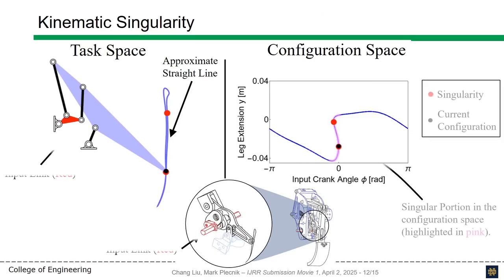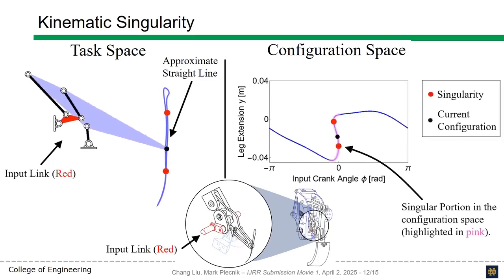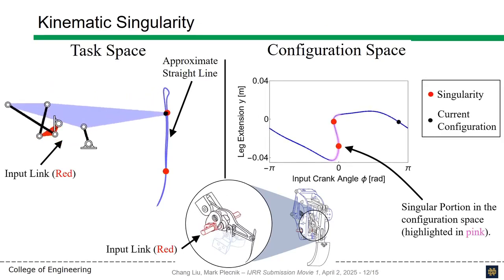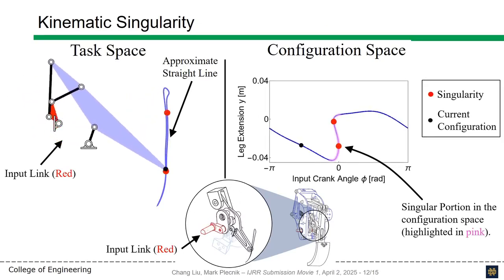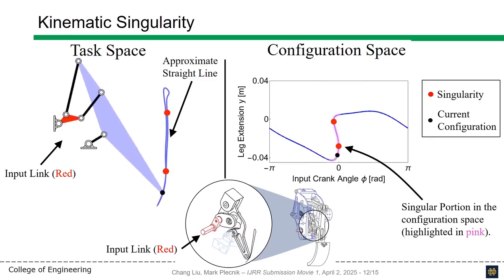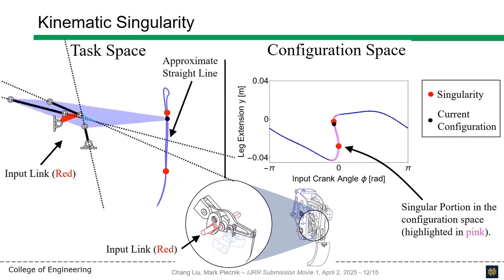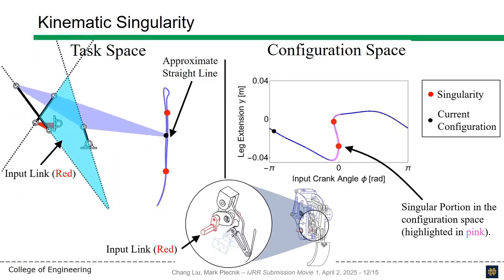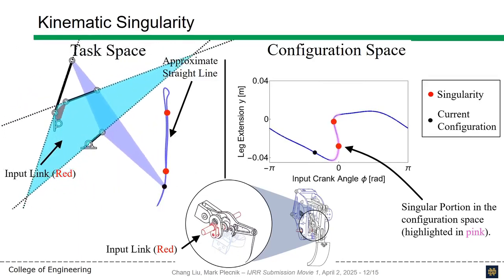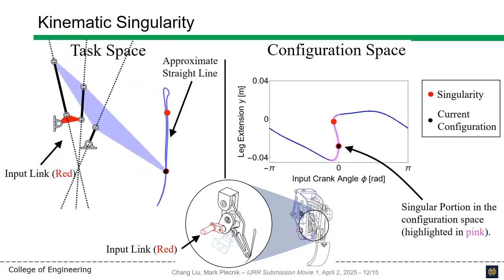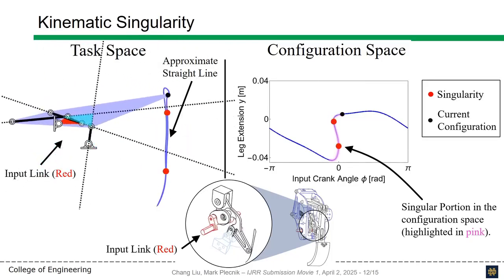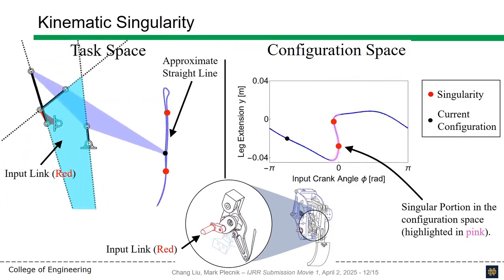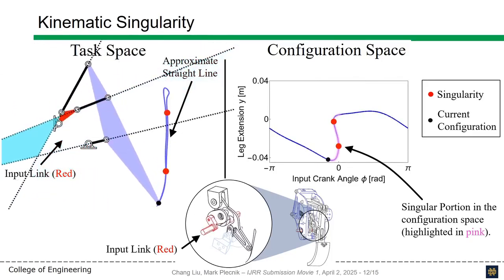The kinematic singularity is apparent in the leg mechanism. When lines along its three binary links, the black links, share a common intersection. Nearness to singularity can be visualized by the area of a cyan triangle bounded by these three lines. A small area indicates it's nearly singular, and from a practical point of view, being near or at a singularity are the same. Note that the cyan triangle remains small over the entirety of the mechanism's upstroke, rather than just instantaneously.